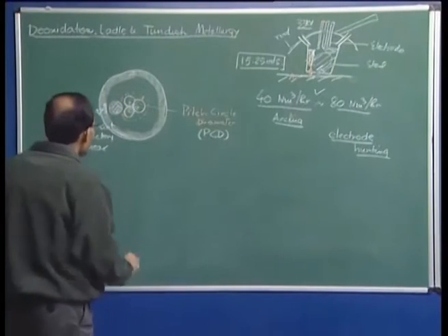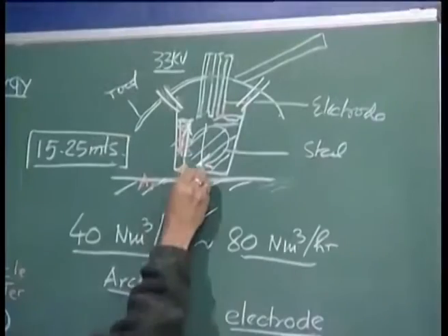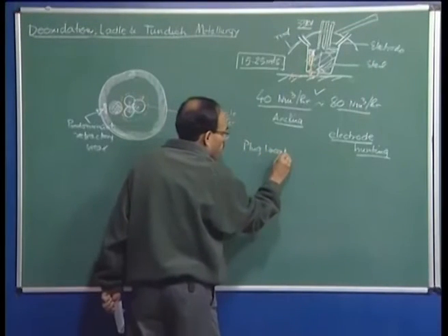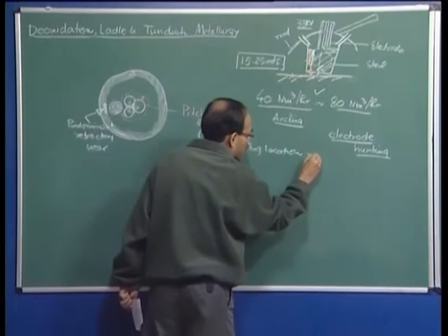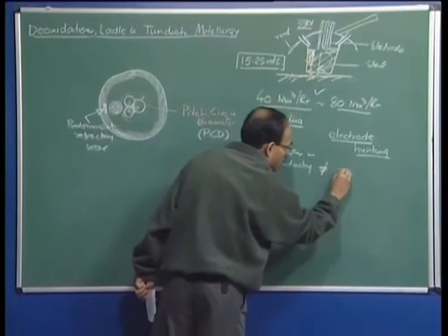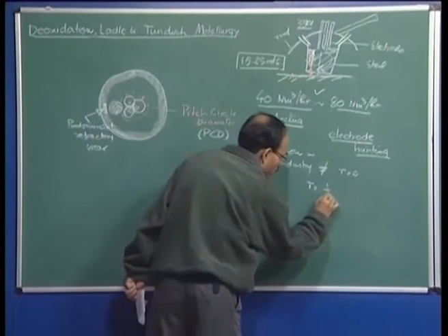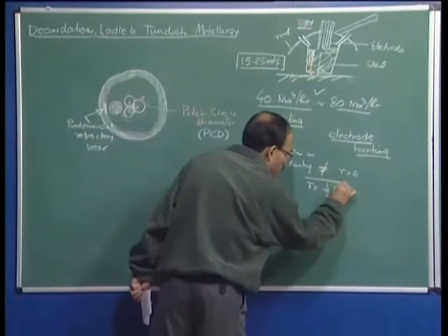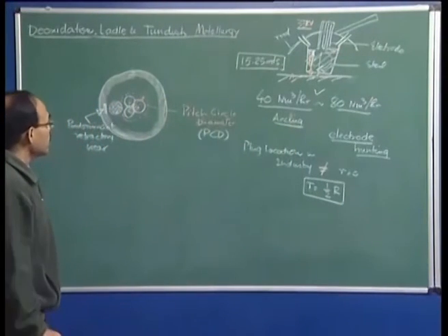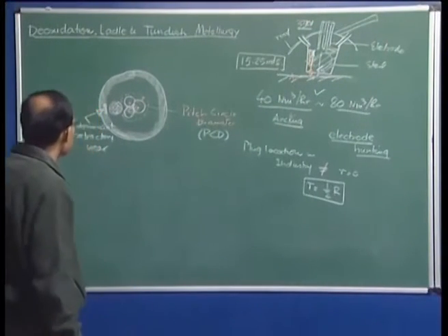significant. So, the typical location of the porous plug basically is at the mid bath radius position. So, the plug location in industry is not at r equal to 0, okay, but it is basically at r equal to mid bath radius position. So, we will always do that. I think having said this much, let us now go to the other section of ladle metallurgy.